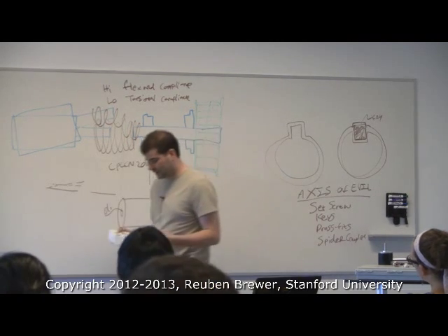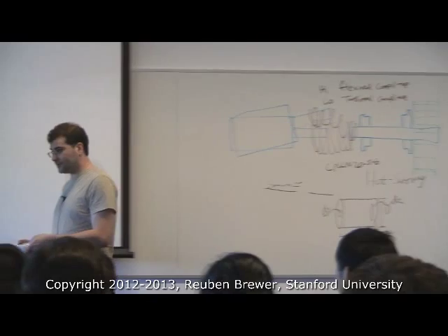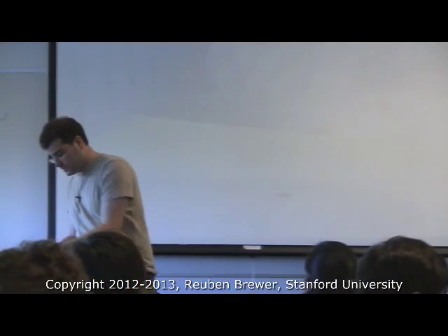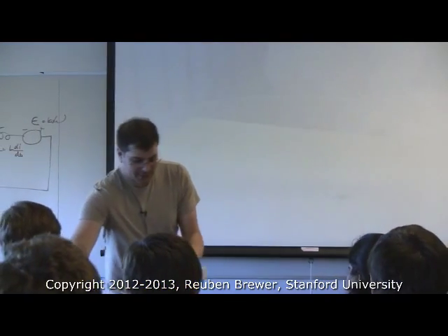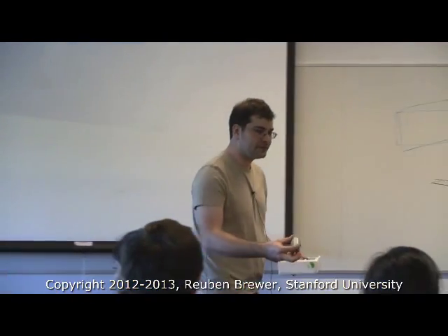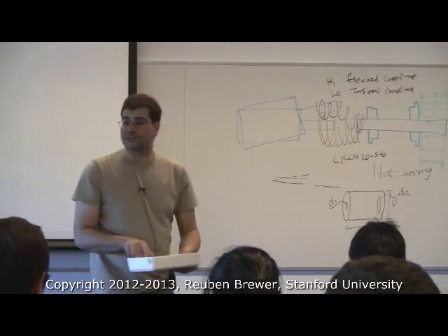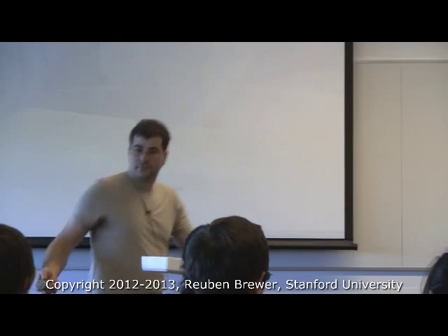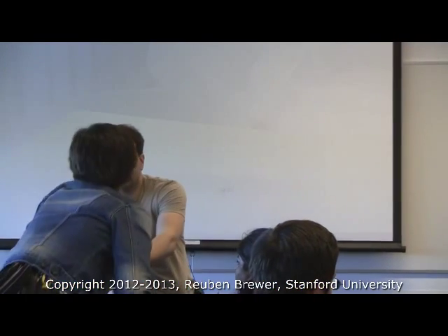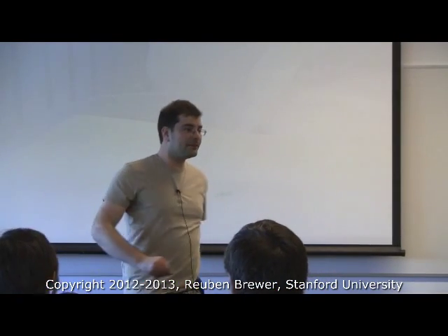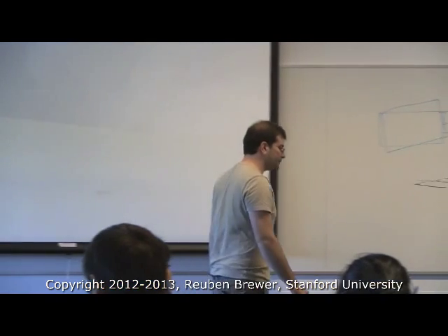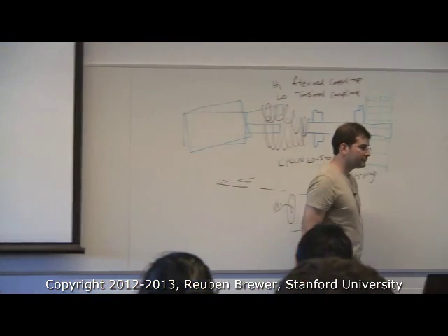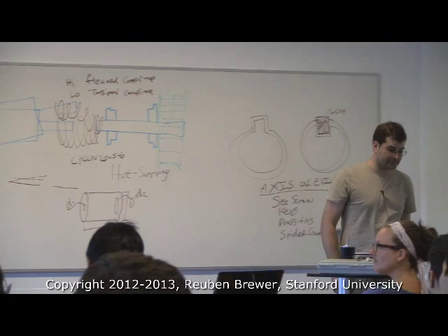Let's talk about cogging. I'm going to hand these out. I need these back at the end of the day. These are cheap Chinese motors that I think go in drills. I want you to spin them. Just take the box, spin them, and tell me something obvious about them. They have discrete positions.